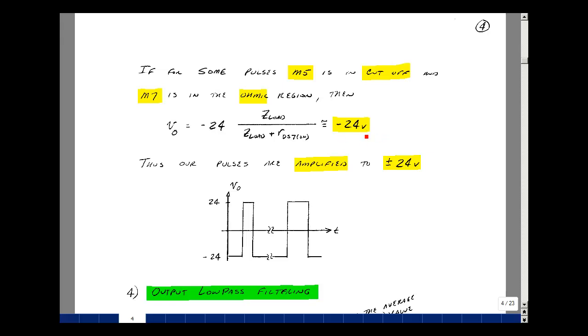What this power amplifier is doing is actually amplifying the pulse. What's going to be coming in is a much smaller voltage that's conditioned by a BJT circuit. And then we're going to use these MOSFETs to basically increase the voltage. So now we've had our pulses and we're going to make them larger. So we've taken our music and converted it into a series of pulses. This is called pulse width modulation.